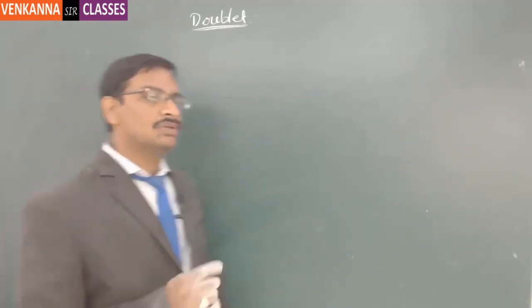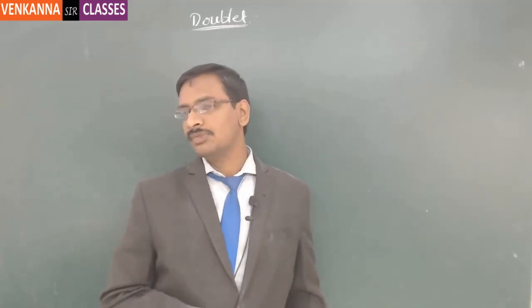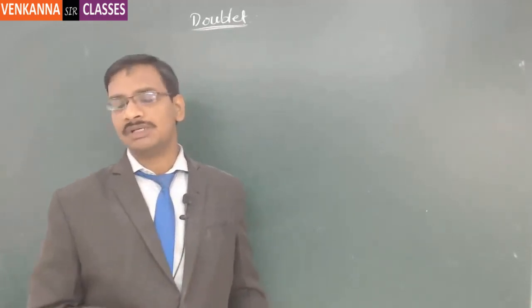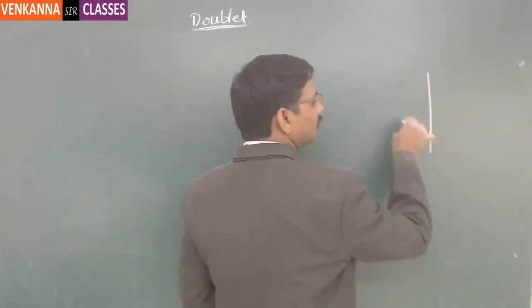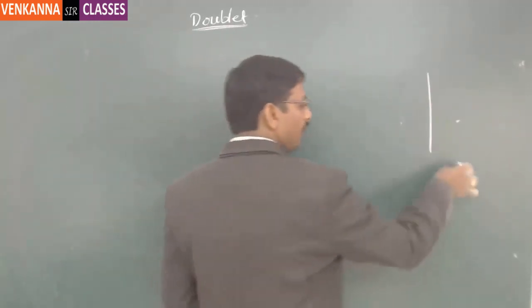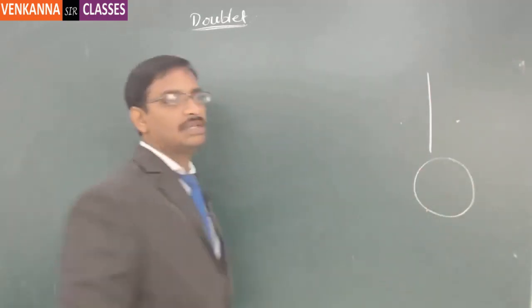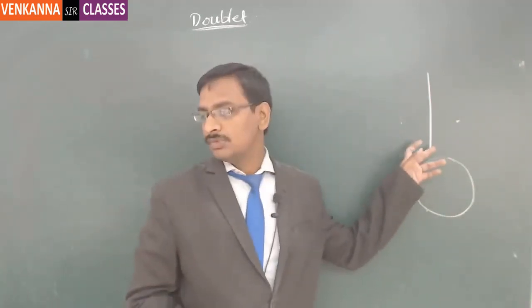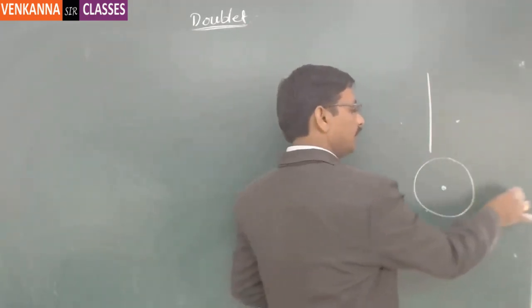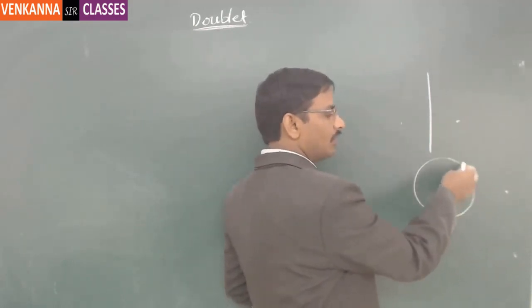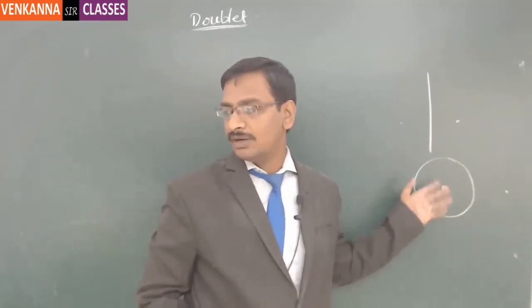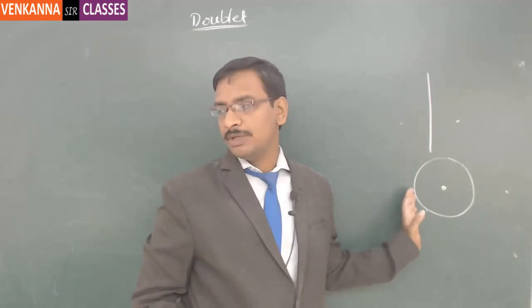Now here, the method of images concept is dependent on the way any particular wall is present or any particular shape is present. Suppose I have a wall, then I have presented one source here and one source here, and then I have accurately modeled it. Suppose I have a pipe like this which is located inside the water, so can I use the same concept? Obviously not, because the flow will not be modeled accurately at all these locations, since the way the streamlines are coming is completely different when the wall is present versus when the pipe is present like this.